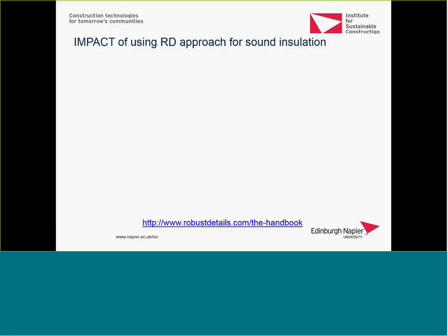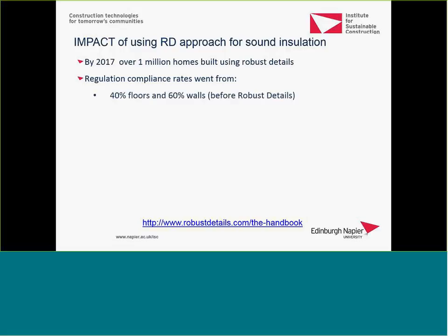The impact of using the RD approach taken further forward, this coming year, the 1 millionth home will be built using the robust details process. The regulation compliance rates changed from previously, as you saw, before the robust details approach, we had a 40% compliance rate for floors, 60% for walls. Within 3 years of the handbook being issued and sites being registered, we moved to 97% compliance, and now it's at 99%, so there's been constant refining and improvement to what we try to do.